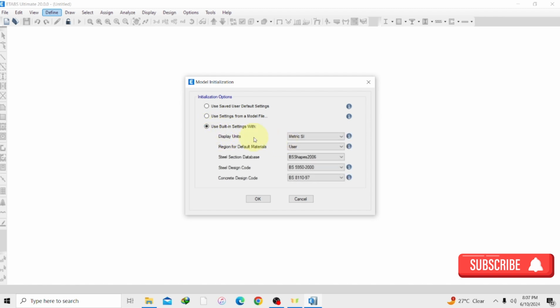And we have display units. Depending on the units of measurement you are working in, you just change it. We have US customary, we have metric SI, we have metric MKS. If you are working in feet, inches or kips, you can select US customary. If you are working in kilonewton, meters, millimeters, you select the metric SI. Since we'll be working in kilonewton and meters, we have to select the metric SI. So based on your units of measurement, you just select that one.